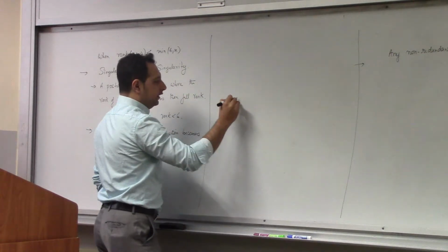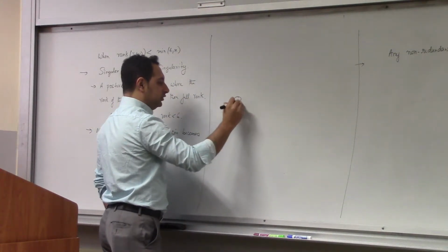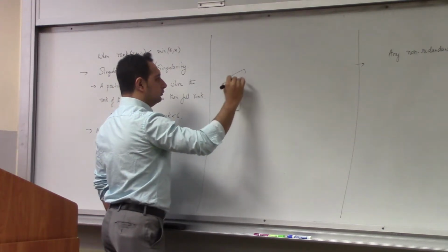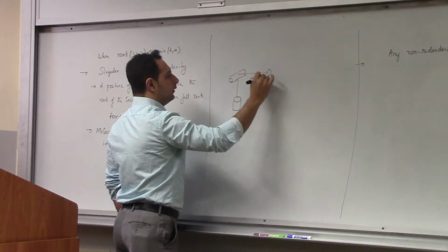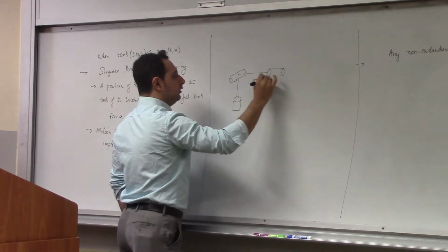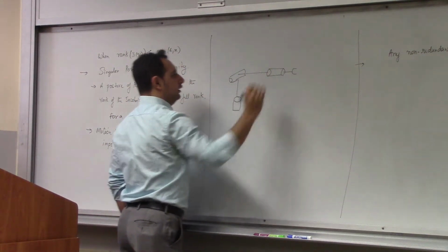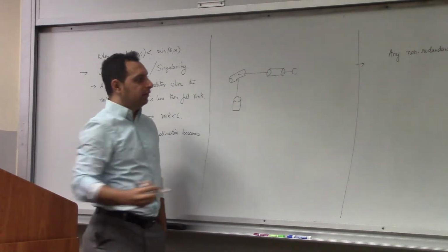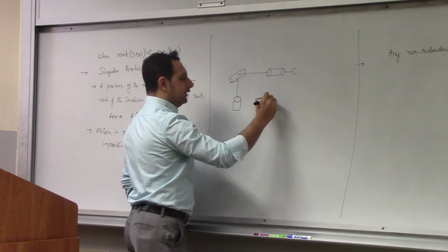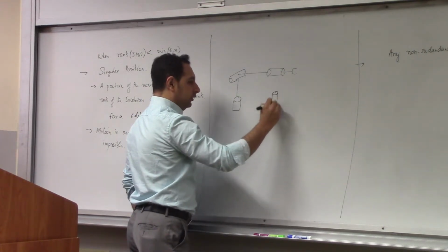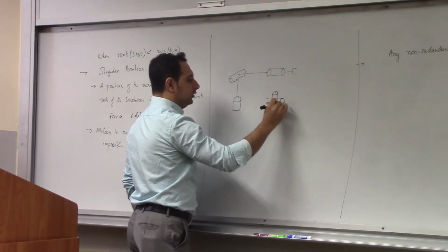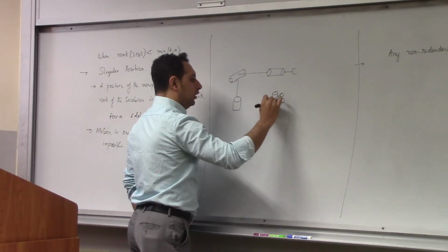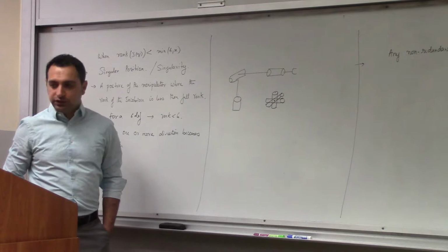We have a configuration like this, right? We discussed the wrist. This was the wrist configuration. Okay, we'll talk about a wrist singularity. This is an example of a wrist singularity. All right. Now, this is a spherical wrist. So a spherical wrist is basically like this, right? You have 3 intersecting joints. This is the second joint. They're all at one point, the wrist center, as we discussed, right?